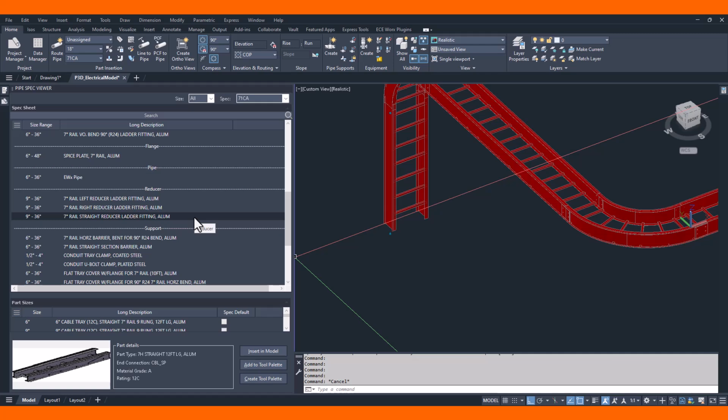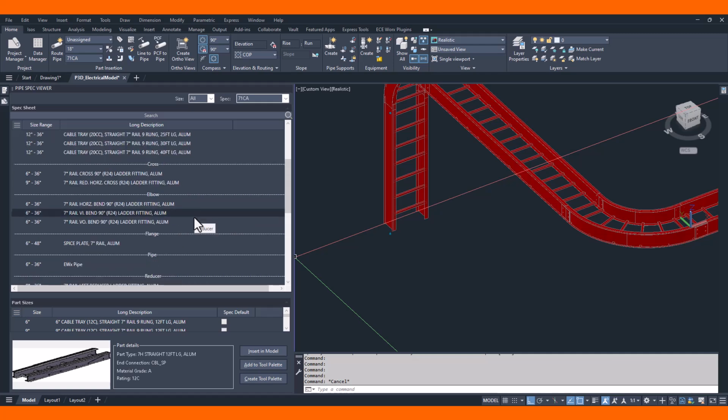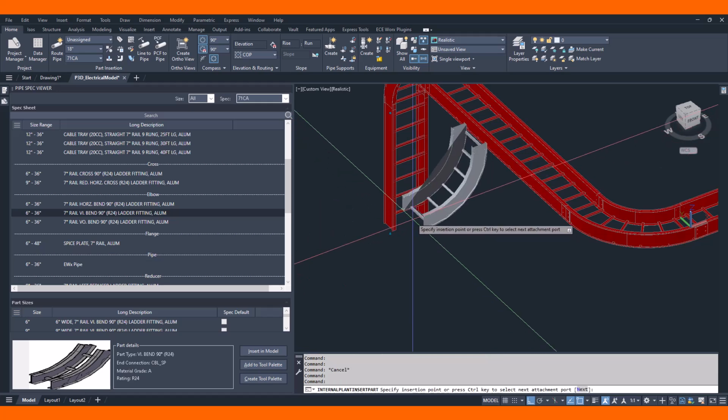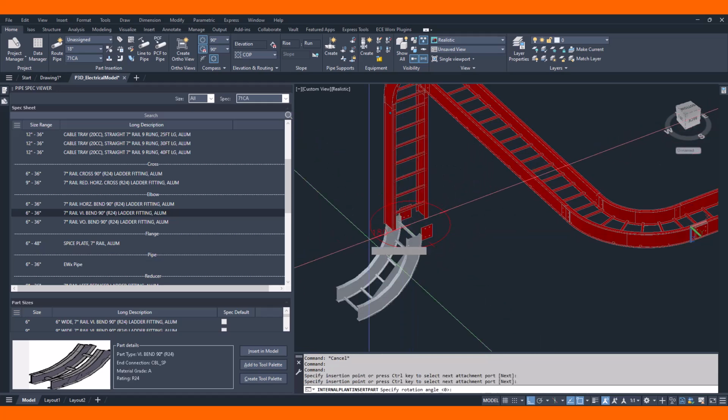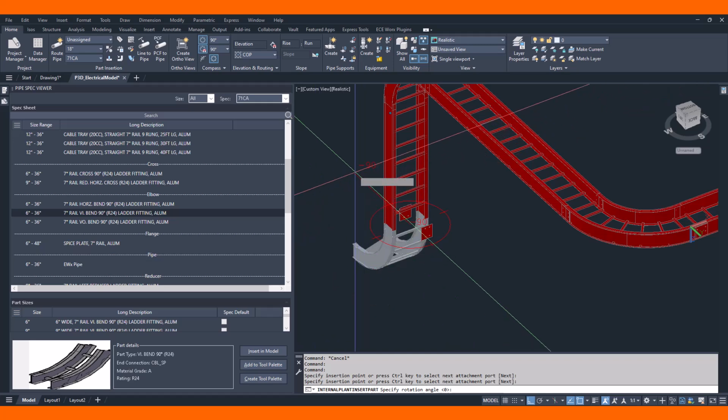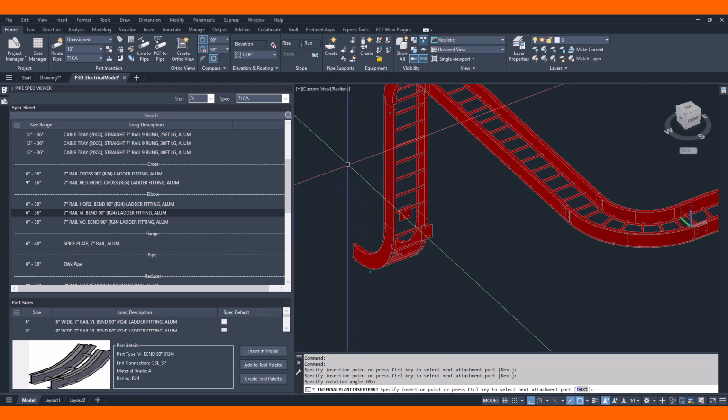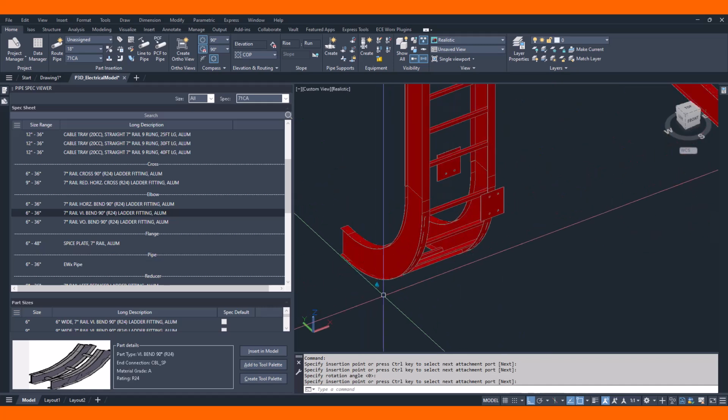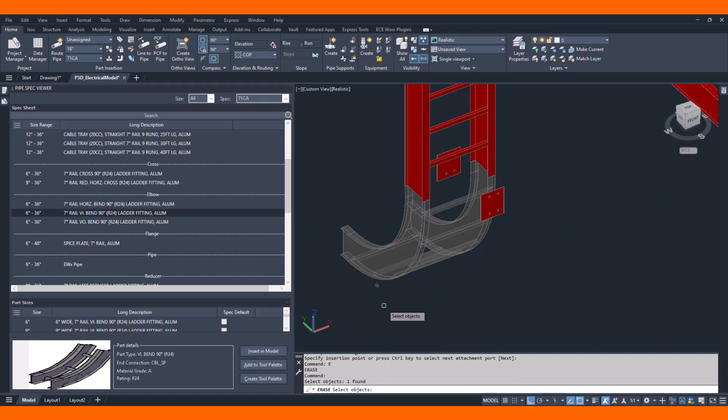Well, so far so good. That was easy. Now I'm going to present perhaps the most challenging part of routing cable tray with ELECTROWorx parts, and that is the orientation of a splice plate. This is a known issue where we orientate a component and the splice plate is rotated at 90 degrees. These splice plates are coming in automatically, which is nice, but in this case, the orientation is such that Plant 3D cannot orientate them as the components are aligned.